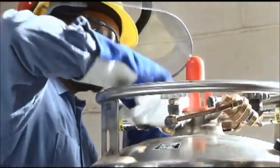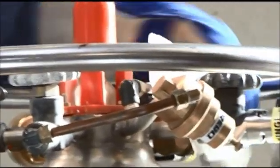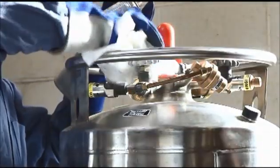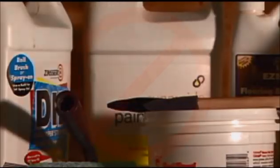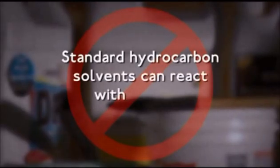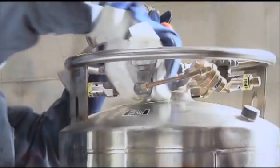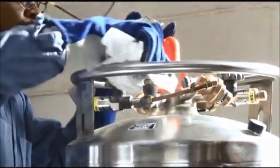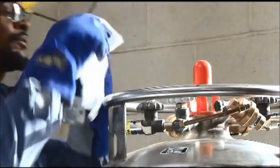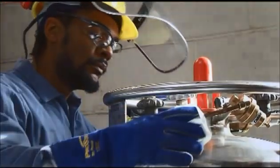Oxygen equipment and systems need to be cleaned of contaminants before introducing oxygen. But standard hydrocarbon solvents such as mineral spirits can react with oxygen, so never even consider using these solvents for cleaning oxygen piping systems and their components. Only special cleaning agents approved for oxygen surfaces can be used to prepare oxygen contact surfaces.